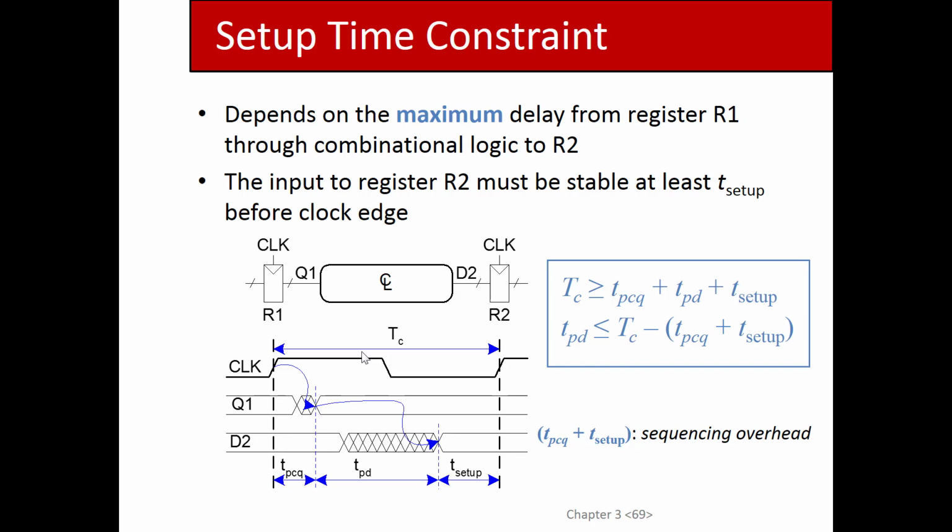How do you do that? Oh, use the Boolean theorems. You can change the logic. You can make trade-offs. You might be able to do something in here that gives you the same logic value with a different propagation delay. You guys remember that, right? I talked about why we have those Boolean theorems, because you can use them to make transformations that give you the same Boolean function, the same truth table, the same behavior, but maybe a shorter path. You guys with me? Right?